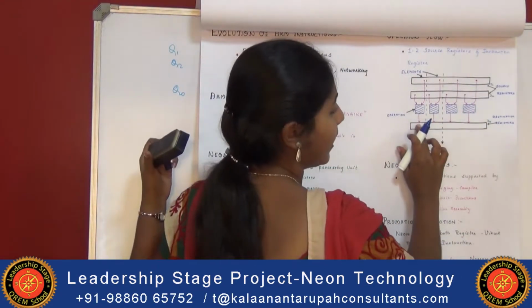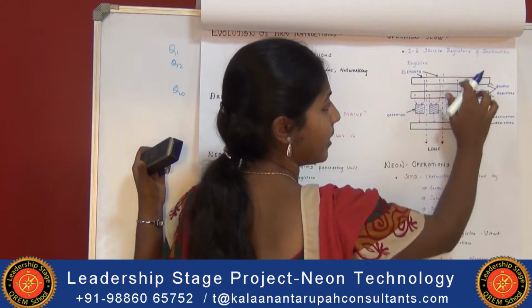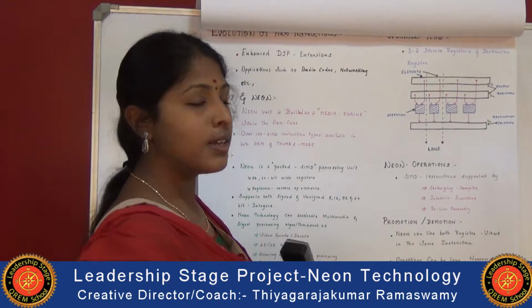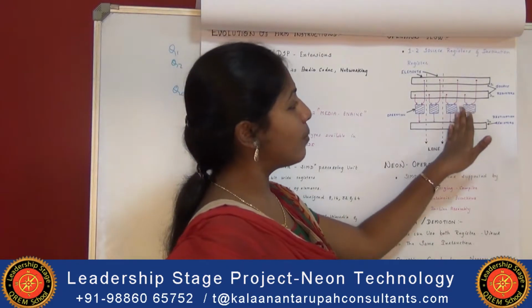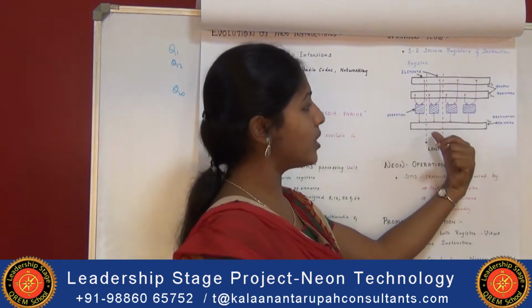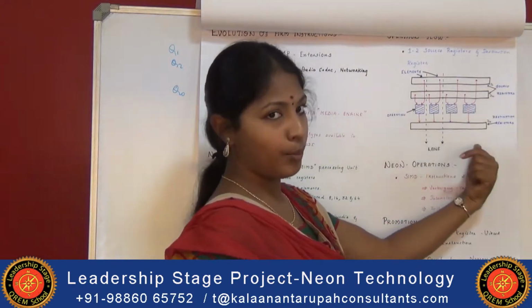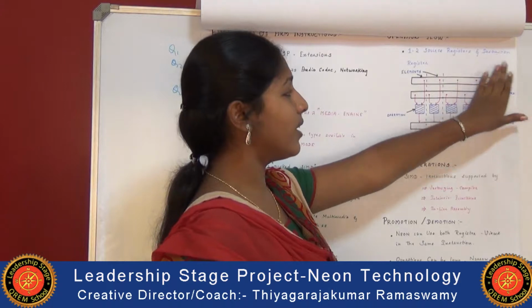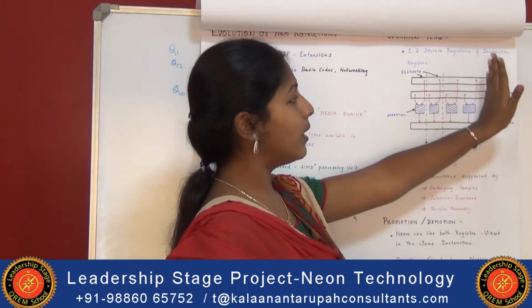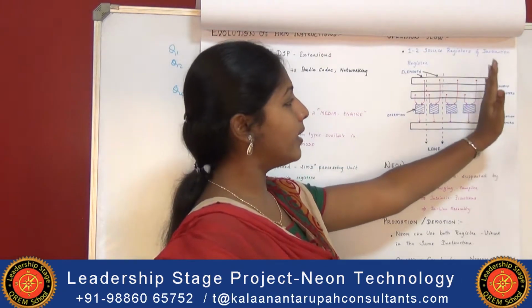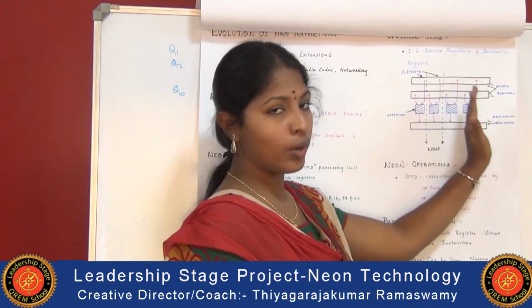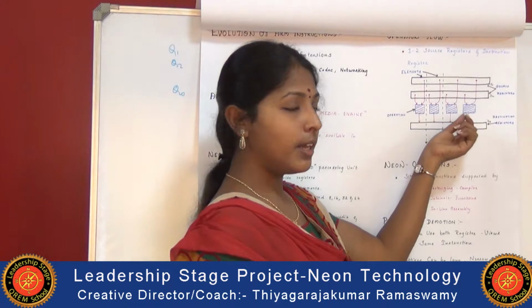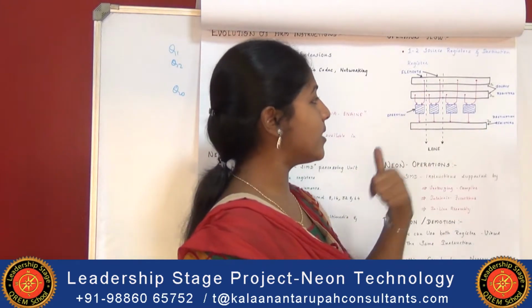Here this is the first lane, the second lane, the third lane, and the fourth lane. The 4 lanes have 16-bit elements. The 4 lanes of 16-bit elements are processed for the same operation and produce the output. So when the instruction is given, Q1 and Q2 take the instruction and it performs the same operation in all the 4 lanes of 16-bit elements, and it produces the output. That output is stored as a result in Q0, the destination register.